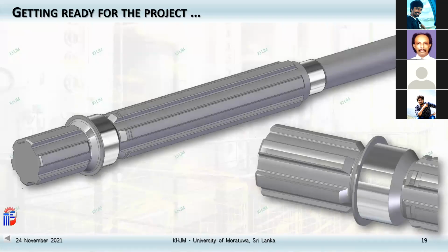I mean, those details are available, but maybe not as you want. So you decide, how do I put them, and then how do I manufacture them? I should be able to machine them. I should be able to take the dimensions out of that one. And at the end, you should satisfy your design calculations as well. So for example, the minimum shaft diameter, right?